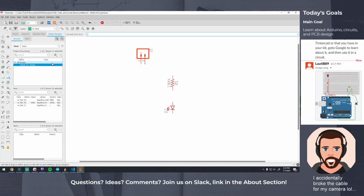Okay, so the next step is to add traces. And so traces are to circuit boards as jumper wires are to breadboards, and they're the way that the electricity actually gets around from part to part. So the two ways to do it is you can either click on net and you can click and drag about to create them.